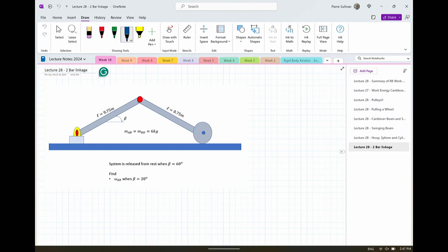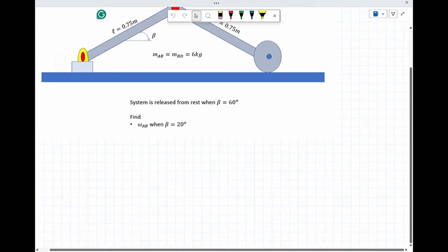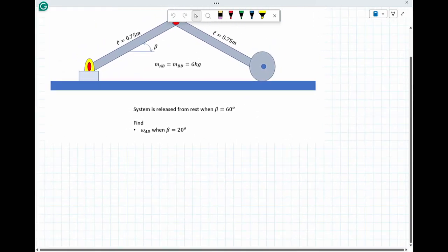But on the second mass over here, it's going to be Vg, omega L over 2, plus a translational velocity. And I need to consider that as I'm referencing everything using relative velocities. So I'm just asking at this point for omega AB.